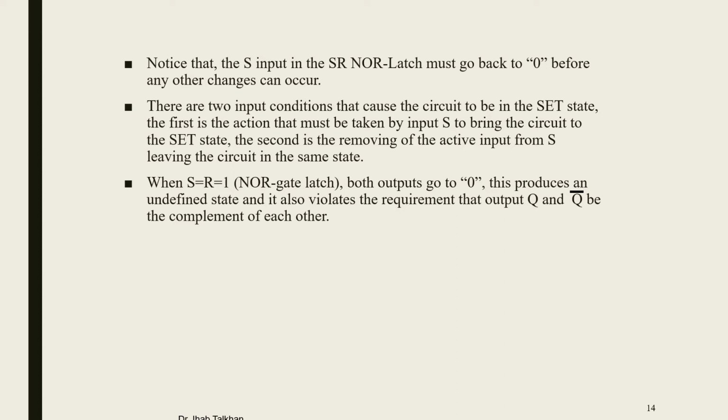When S equal R equal 1, no states latch, both outputs go to 0. This produces an undefined state, and it also violates the requirement that outputs Q and Q bar be the complement of each other. This is actually what we discussed when we talked about the NOR gate latch, but I'm just repeating it here to remind you.